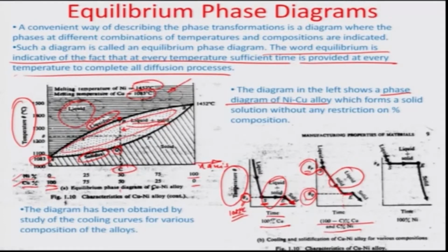So there is going to be a latent heat phase in the solid, and then it is going to go down. So basically what you are trying to do when the phase changes from a single phase into two phases is take this region and split it up into this fall in temperature versus time, where there is partial liquid, partial solid, and the latent heat part which is separate, and this latent heat part keeps on changing as the percentage of nickel changes.